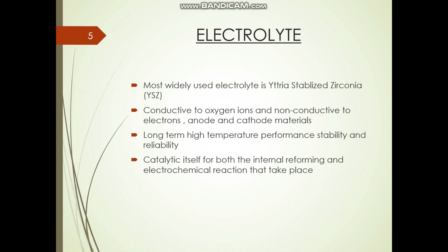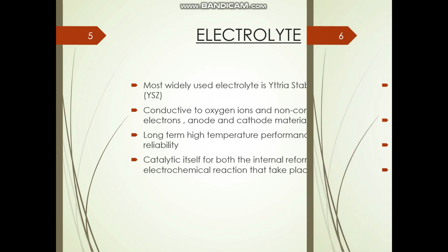Now, talking about the constituents of SOFC. First is the electrolyte. The most widely used electrolyte is yttria stabilized zirconia. It's majorly due to this ceramic material that SOFC are operated at high temperature, since above a particular temperature, it only conducts oxygen ions and is non-conductive to electrons, thus behaving as a perfect electrolyte. Moreover, it also shows catalytic effects to both chemical reactions taking place in this fuel cell.